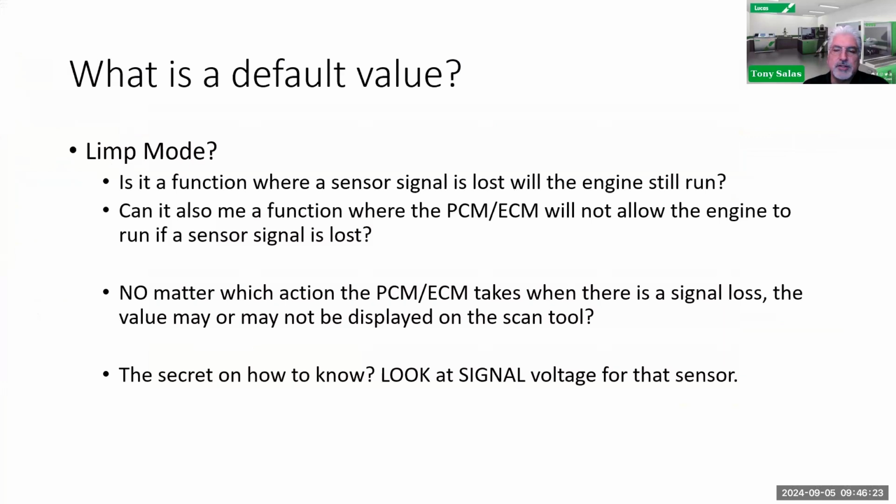What's the classic one on a 6.4? If you disconnect EGT1, exhaust gas temperature 1, and you leave it disconnected, that open circuit is going to show a default value of over 1200 degrees on the scan tool. At that point, you're going to reconnect it. It's going to actually read correctly, but the computer still thinks it's hot, so you will get a no crank, no start condition, right? The book says you've got to wait 30 minutes with the key on with that set.